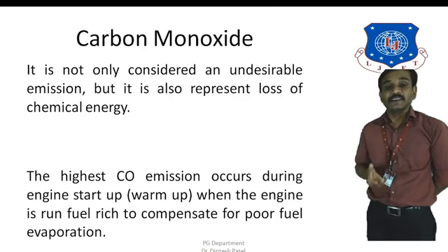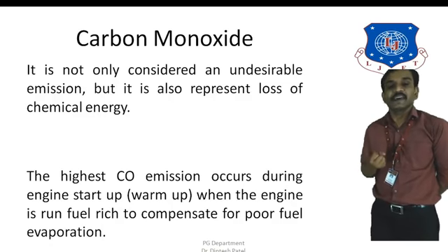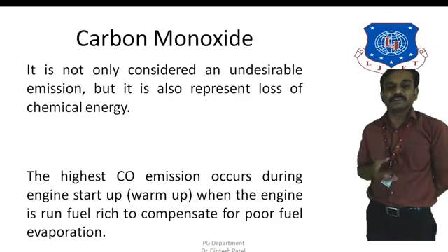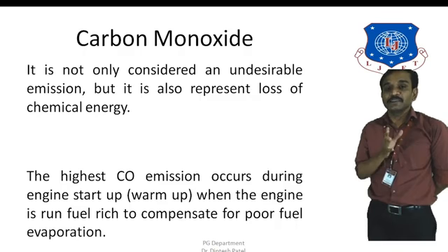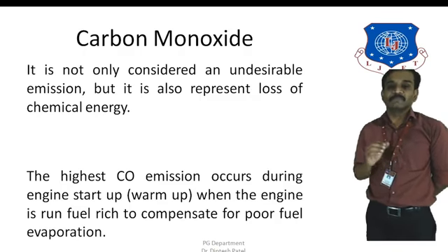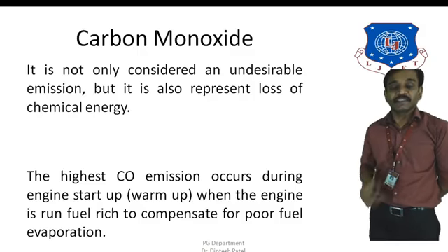As I said earlier, during the warm-up the engine requires a rich mixture, and whenever there is a rich mixture, it will have higher carbon monoxide. So carbon monoxide will be highest especially when the vehicle starts, when the vehicle is moving uphill, or when it is at high speed.